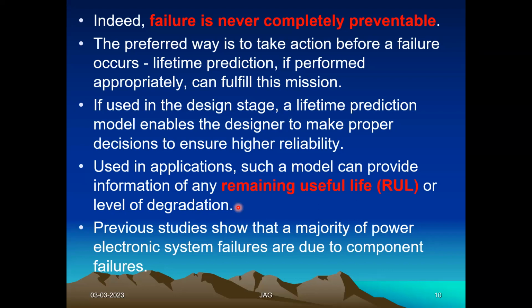So if you exactly identify the RUL, what is the advantage? We can schedule a maintenance. We can schedule a repair. We need not wait for the breakdown to occur and then take a corrective or repair action. That is the beauty of condition monitoring, through which the RUL can very well be predicted. Even without condition monitoring, manufacturers give the MTBF, and the MTBF minus the used hours will give you the remaining useful life. That calculation is again a nice way of handling the issue to improve the reliability and availability.